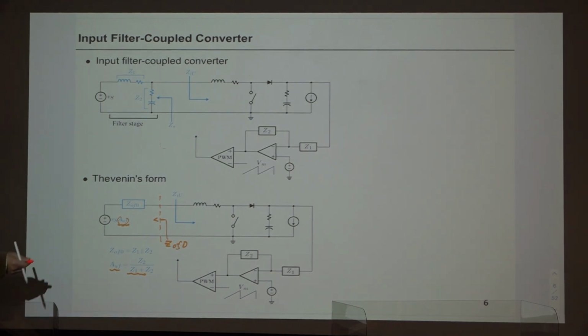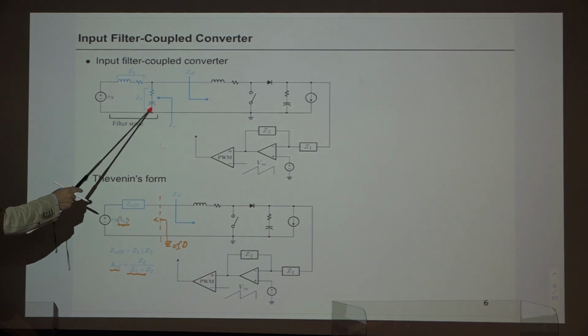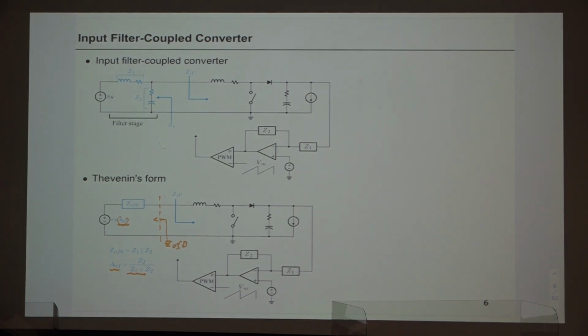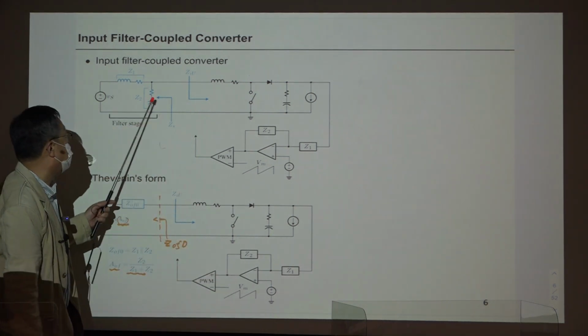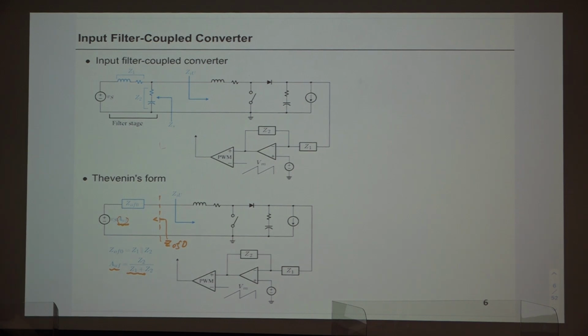And another thing is, you employed this inductor, you applied a capacitor here, then you are expecting a current attenuation of minus 40 dB per decade. Because you employed two reactive components, each of them will provide 20 dB attenuation, and you have another 20 dB attenuation, then they will provide 40 dB attenuation at high frequency, something like this. Okay, so this should be this attenuation, but it is impossible for this structure.